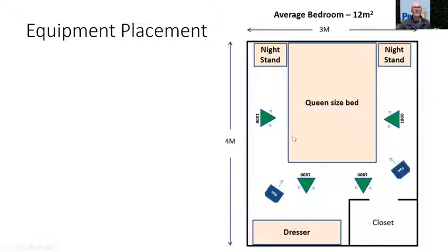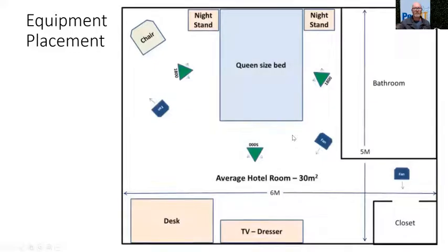If I was to go to a larger room, I would generally be looking at a room of 25 to 30 square meters, hotel rooms also being a little bit larger in a lot of cases. I'm going to need about 9 kilowatts, or if I'm using 3-phase power, I have 2 heaters in there, and that would be 18 kilowatts. But here in this case, I've got an 1800 watt heater, an 1800 watt and a 5000 watt heater. Collectively, that's about 9 kilowatts of power output. And I've got 3 fans here strategically placed just to move the air around.